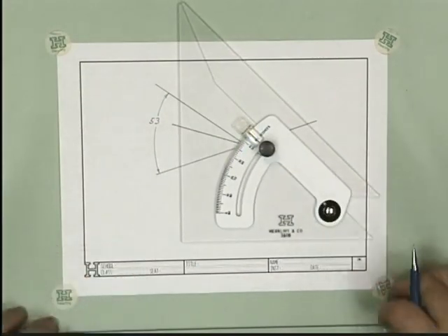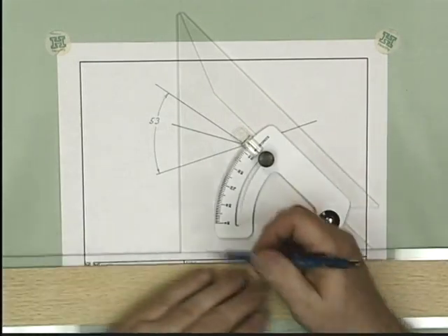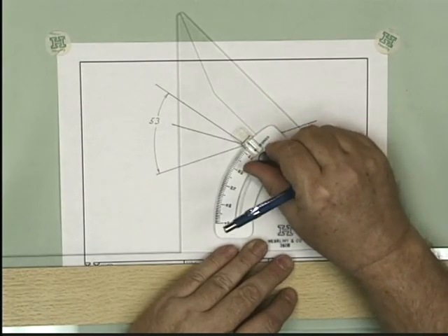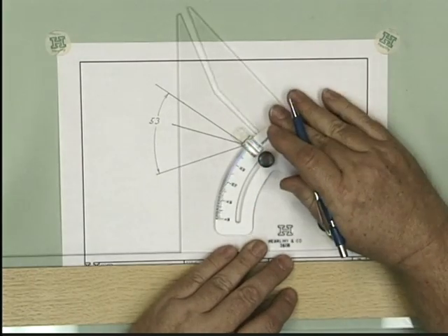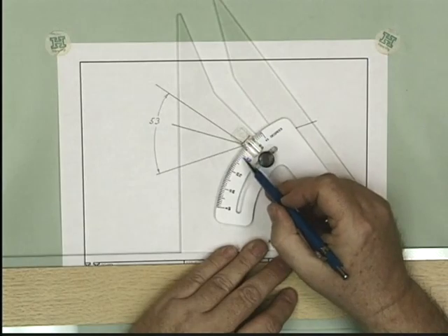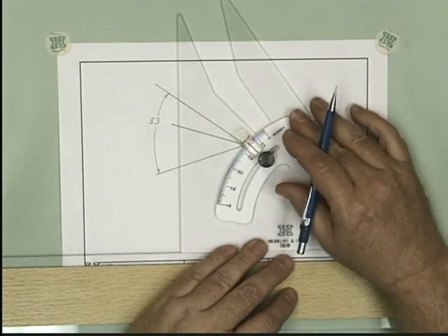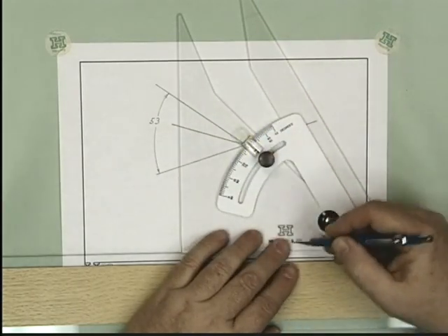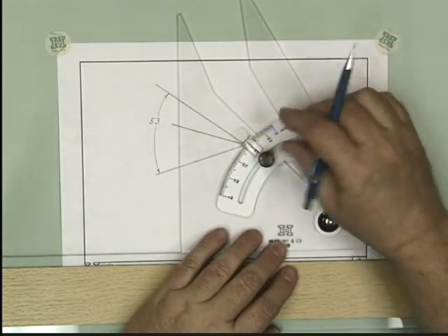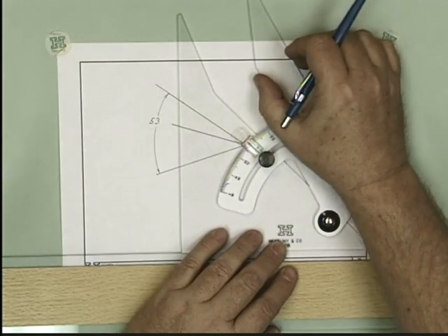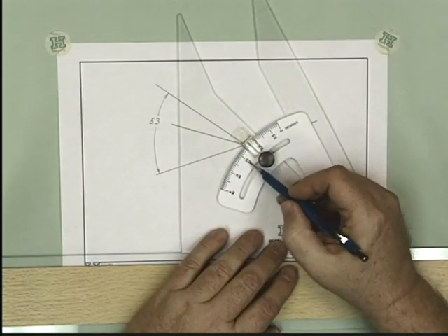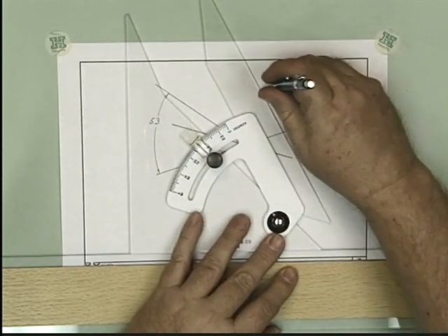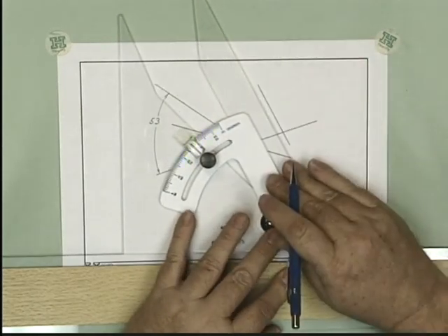Now this triangle starts out with a 90-degree angle and a 45-degree angle, but it has this little thumb screw that you can loosen up, and then you can adjust this. And there's a little built-in partial protractor right there. So if I want to make an angle here with the horizontal, I can adjust this until the reading on my mini protractor is what I want. Set this, slide it to the point that I want, and make lines at that angle.